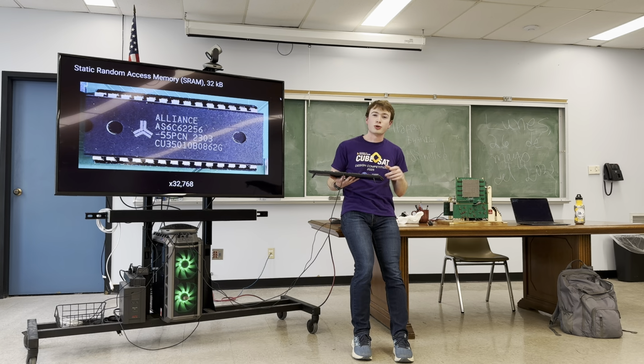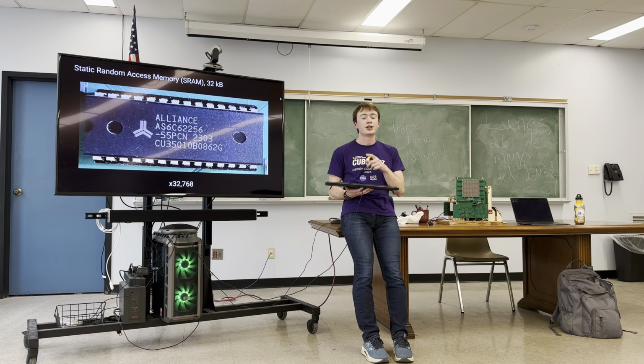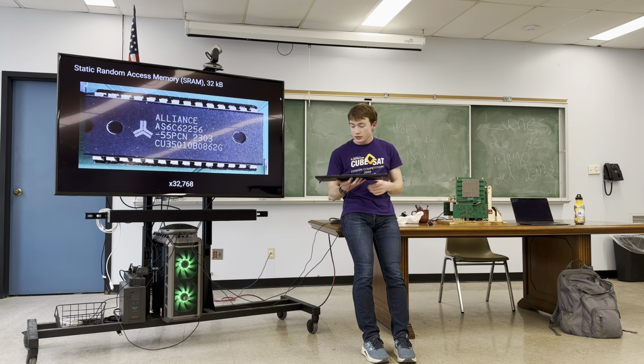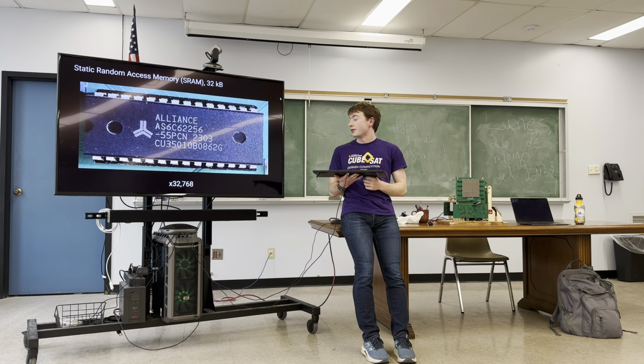And there's some more complicated logic to control which one is selected to be written to or read from at any time. They're all of the outputs connected together to one bus, so-called. That's why it's important for them to be able to turn their outputs off, because you don't want multiple gates connected the same way, because then it'll cause a short circuit when the outputs are set differently.